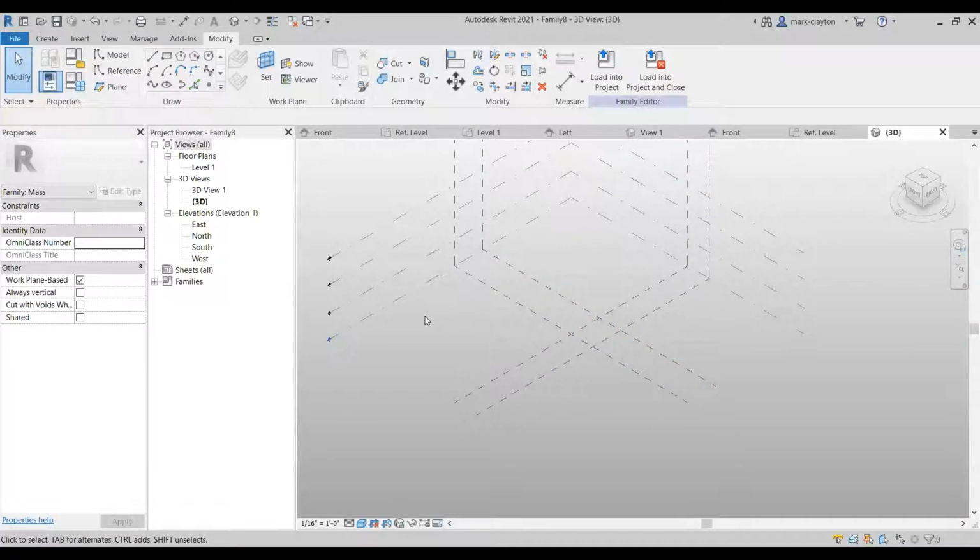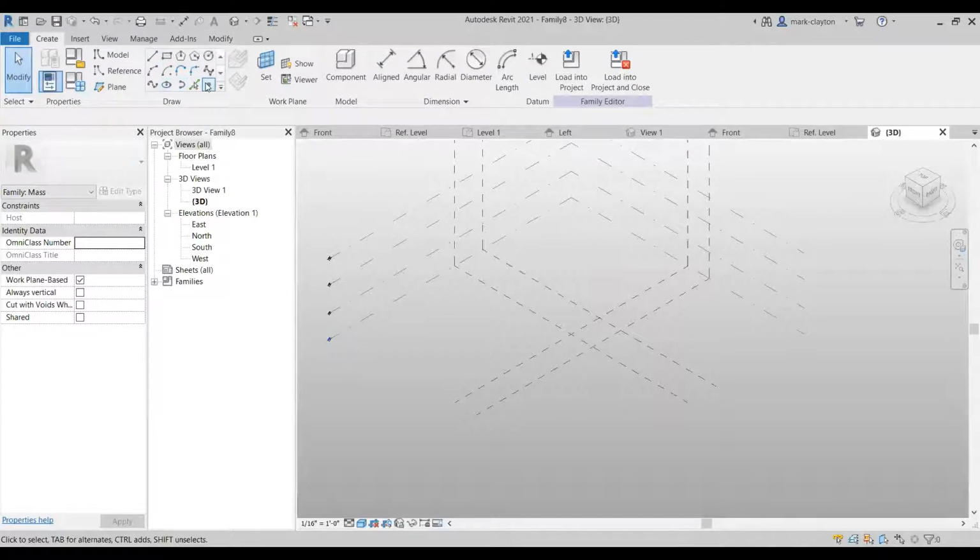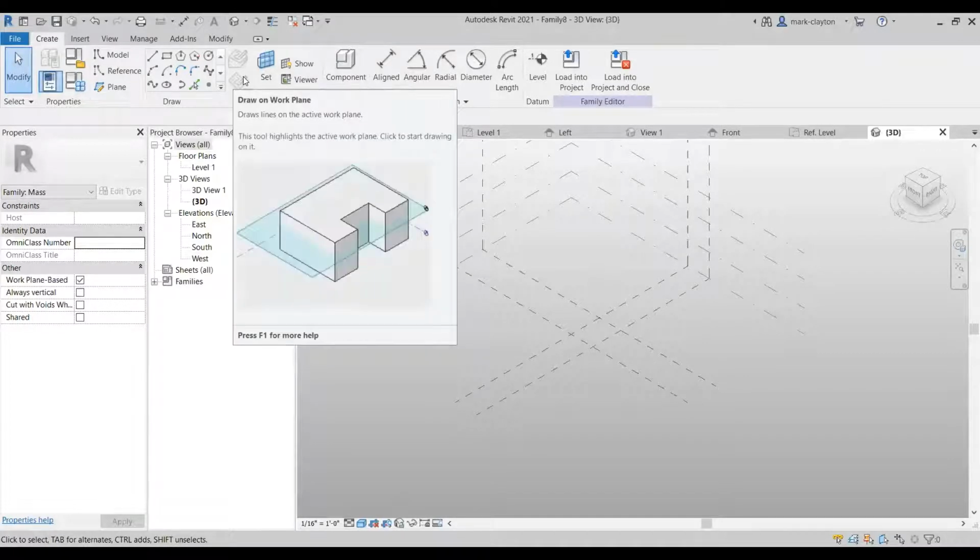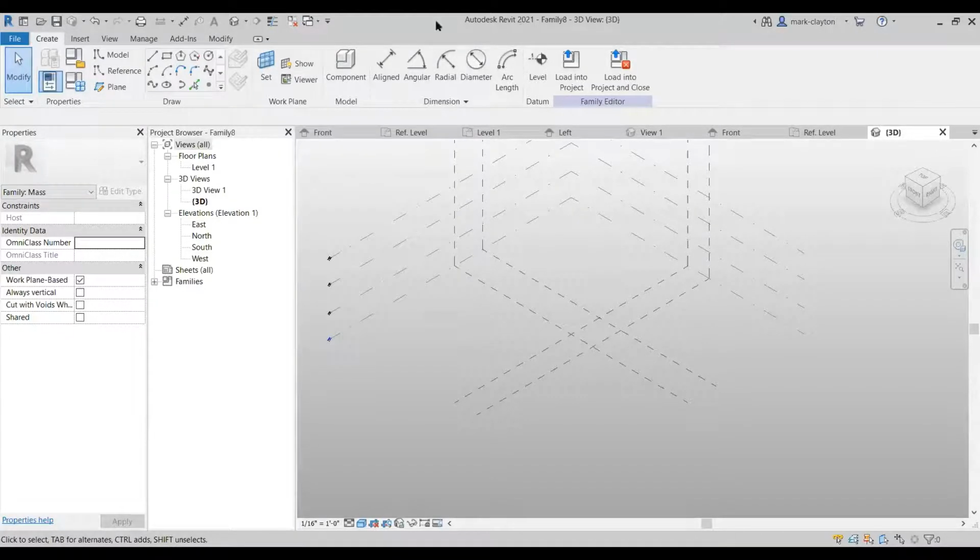But so we can start with the Create tool, and you'll notice that the family editor had extrusion and revolve and sweep and all that. The conceptual mass editor does not have that range of tools. However, it can create all those things. It has a rather weird attitude of draw it first and it will figure out what you're trying to do. And we can watch that.